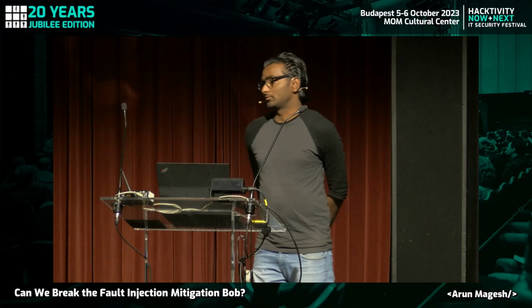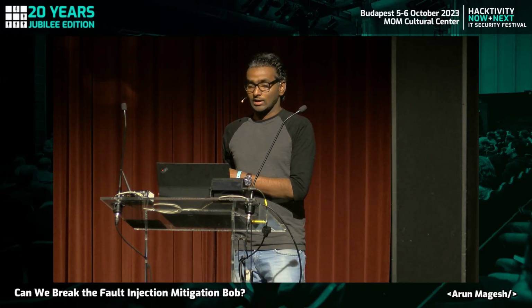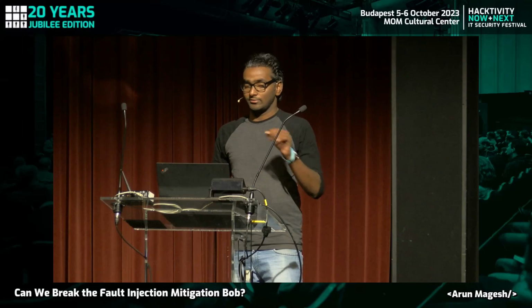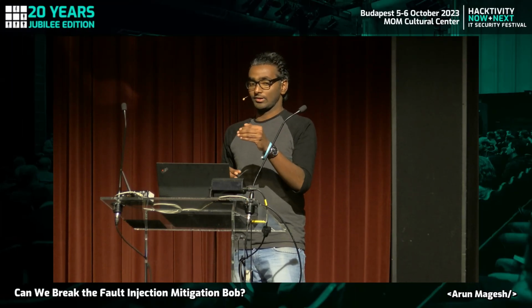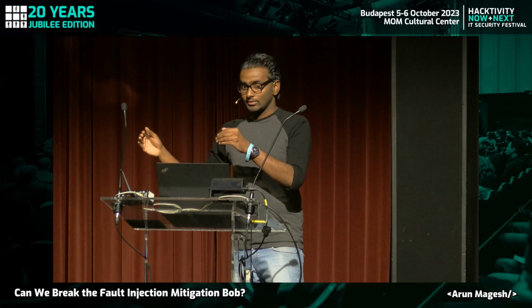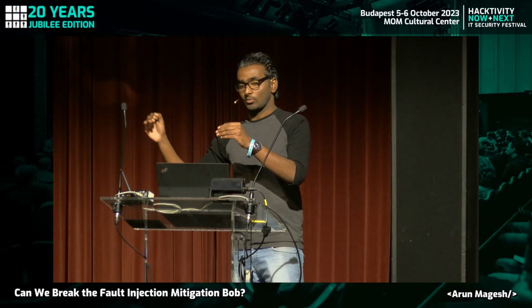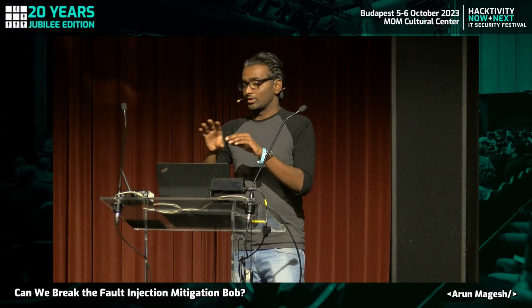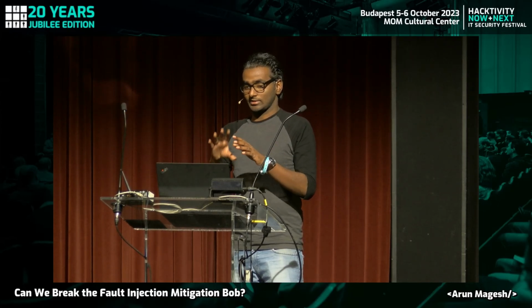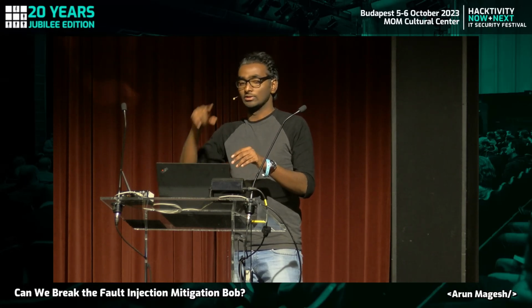For example, if your code flow sets a value in your machine, let's say you're enabling a feature, and there's a check that says if the password is correct, enable a bit in memory to enable some secret feature. If you glitch there and can set that value, the feature will be persistent, but the glitch is not persistent. It will only work as long as the glitch worked, and if you restart it, your code will work as normal.